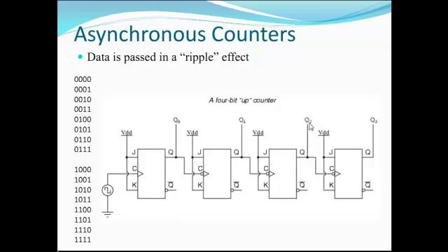Q0, Q1, Q2, and Q3 are the counter outputs, where Q0 is the least significant bit. After the first falling edge of this clock signal, which is only applied to the first JK flip-flop, the initial state where Q is 0, 0, 0, 0 will be changed so that the least significant bit will be inverted, so that Q is then 0, 0, 0, 1. Since this Q0 is going from 0 to 1, this clock signal input into the second falling edge JK flip-flop does not affect anything, so the rest of the bits remain unchanged.